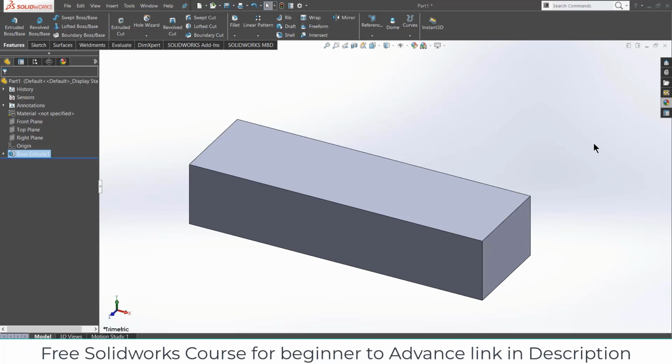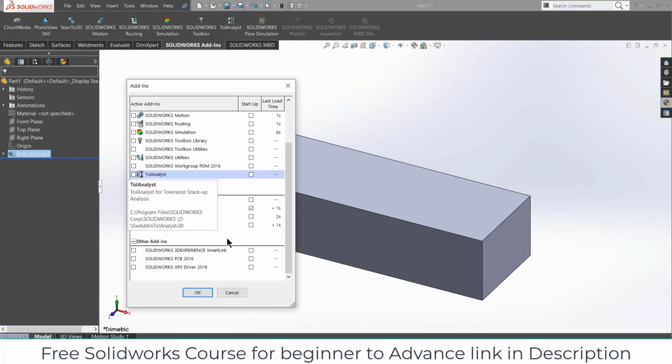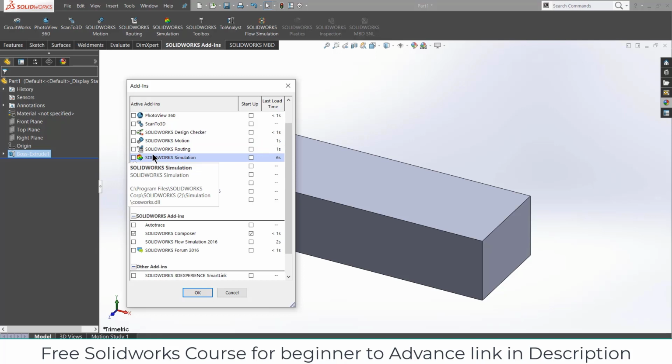So the first thing I have to do is the simple simulation of it. If I go here, you will see there is no SolidWorks simulation tab here. So what I need to do is go to SolidWorks add-in. Here you will see SolidWorks simulation. Another way to see that is go here, click on add-ins and you will see SolidWorks simulation.